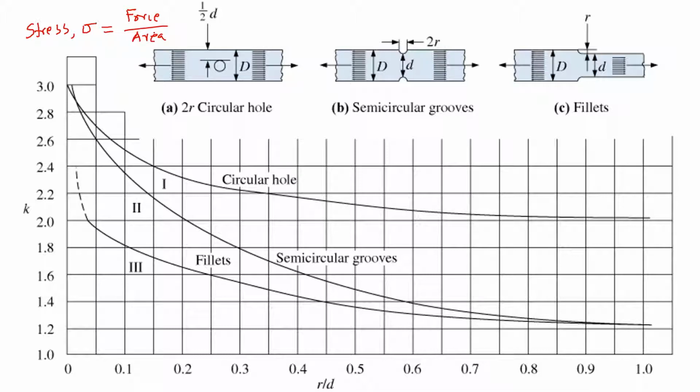In that formula, it doesn't consider the fact that if you have some kind of sharp edge, or even some radius, the stress can concentrate there.